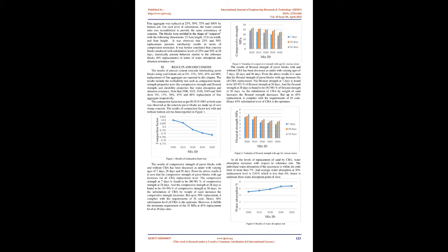It was concluded that at 28 days, the paving made with 5 mm bottom ash size has a lower water absorption than the one with 2 mm size. It was further observed that for the abrasion test, all mixtures performed well under the standard specification of grade A.